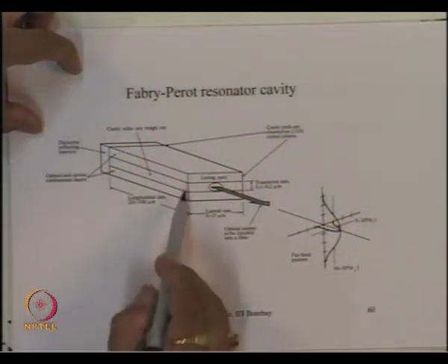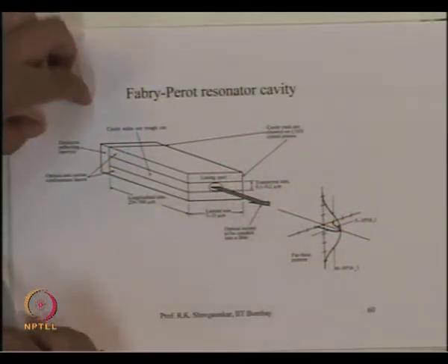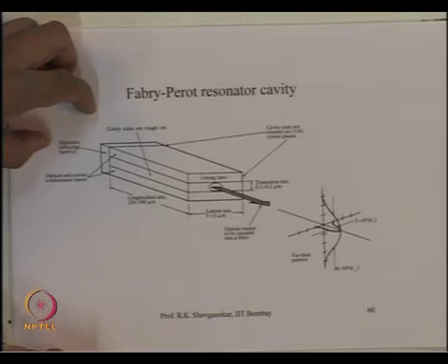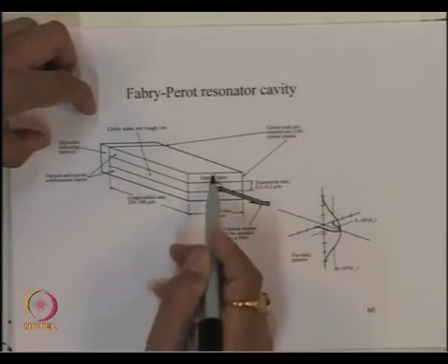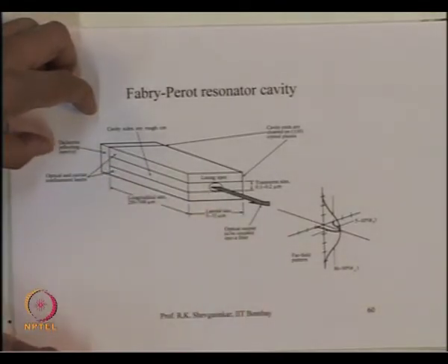So, basically what we find here now is that the laser diode is a very good device which can be suited for long distance optical communication with the digital modulation process. So, schematically, if we now see how the light is coming out, essentially we have a multi-layer structure, and in this region the recombination takes place and the photons are generated. We provide some kind of a feedback or polishing on these faces of the device, and a laser beam comes out of this.